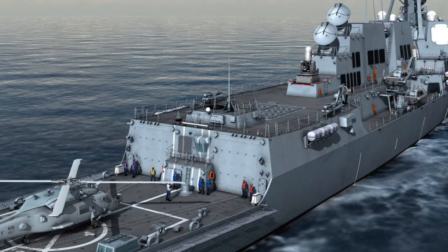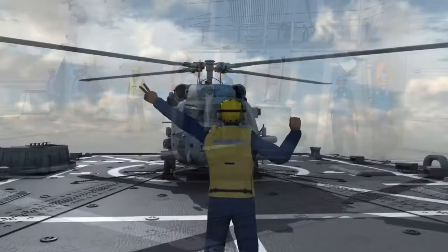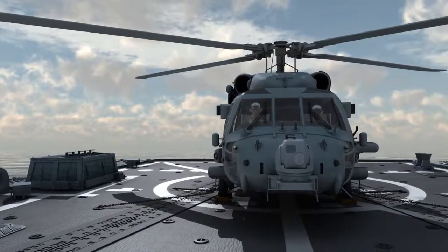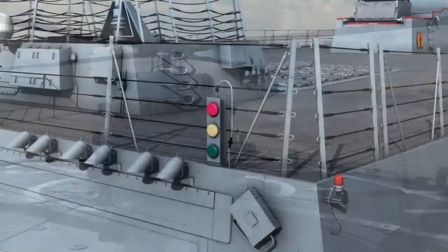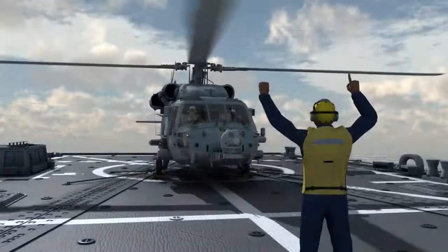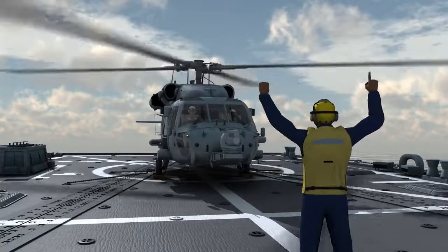Once personnel on the flight deck are assigned, safety equipment is donned and functioning, and the safety brief and FOD walkdown are conducted, the FDO will direct the LSE to report manned and ready to the tower. When signaled by the LSE, the pilot starts the aircraft engines. After verifying that the area is clear and upon approval from the LSO, the LSE signals the pilot to engage rotors once amber deck is set and the pilot is ready.